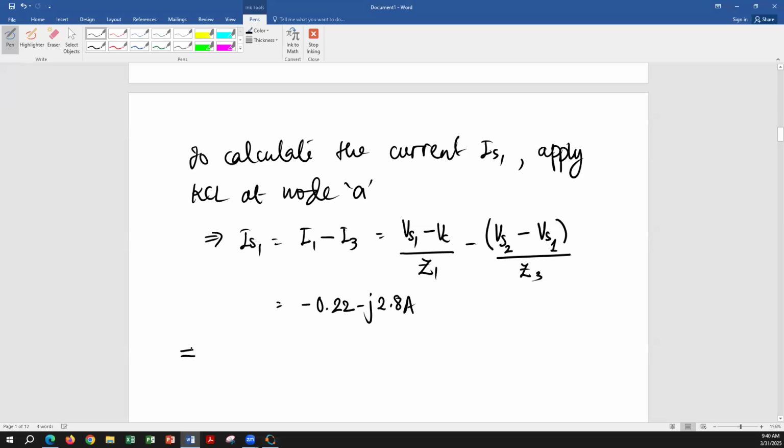So we can calculate parts 1 and 2 now, first, which implies part 1. And we can calculate complex power, because the real part of complex power is going to be the active power and the imaginary part is going to be the reactive power. So instead of calculating them separately, we can calculate just the complex power and look at the real part as the active power and the imaginary part as the reactive power. So complex power of VS1 is, what is the formula?